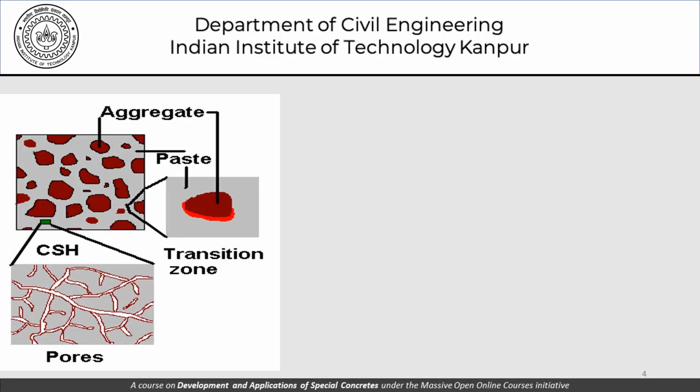Let's recall once again the basic model that we are following as far as concrete is concerned. Here we have the coarse aggregates suspended in mortar, mortar being a suspension of sand, and paste being a suspension of cement particles in water. So once it comes to higher strength concretes, what really changes as far as this model is concerned? That is something which is of concern to us.